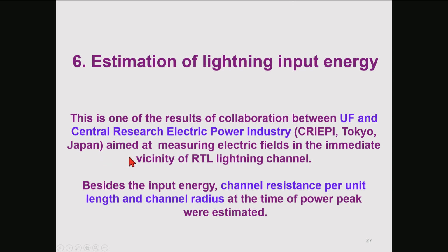That joint experiment was aimed at measuring electric fields in the immediate vicinity of rocket-triggered lightning channel. Immediate vicinity here means 10 centimeters, and Pockels sensors were used for those measurements. Besides the input energy, channel resistance per unit length and channel radius at the time of power peak were estimated.